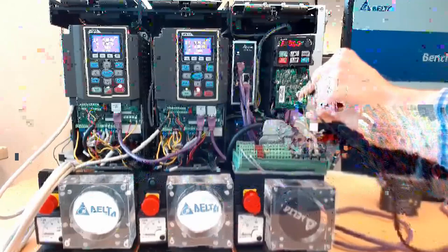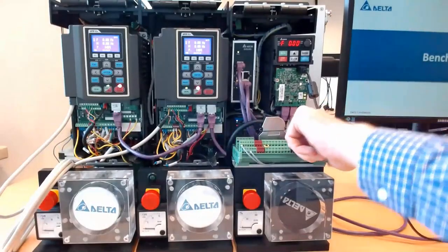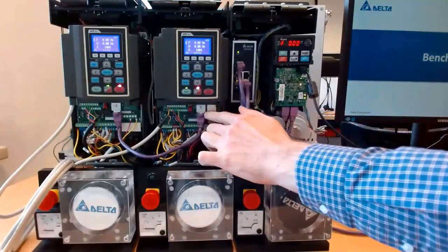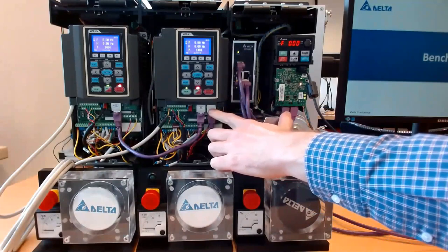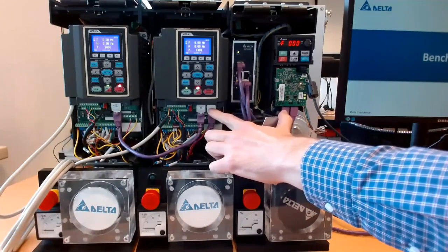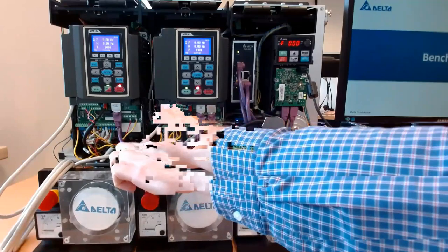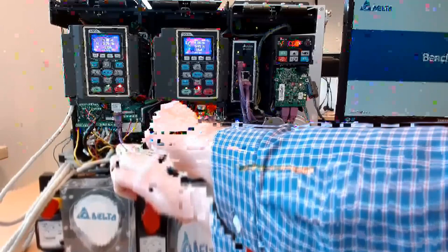I'm also connecting my laptop to this switch, which is connected to an AS200 drive, which is somewhere behind. And then from the switch, I'm also going into a daisy chain connection to the dual port Ethernet IP card. And from this Ethernet IP card, I'm then going into the dual port Ethernet IP card on this follower C2000 drive. And then from it, I'm going into a single port Ethernet IP card, which is connected to another C2000 drive.